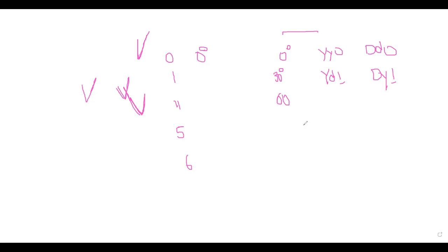So by this, I can summarize that where you can see harmonic content in the system, prefer to go for a delta star for the auxiliary loads. If you have an application for generating stations, delta star is a good one. Delta star 0, delta on the lower side.